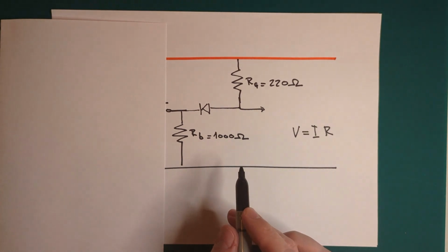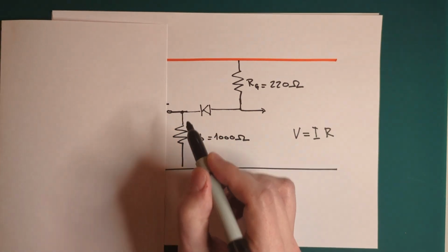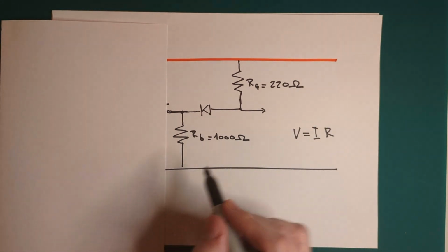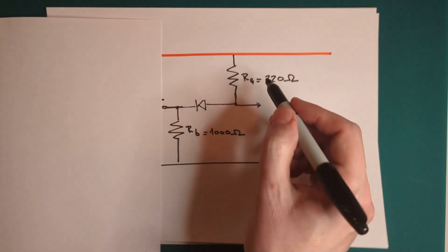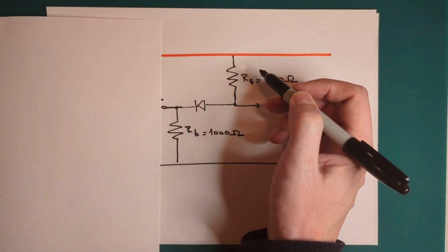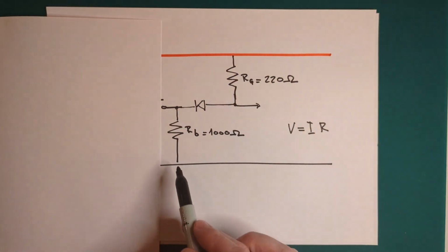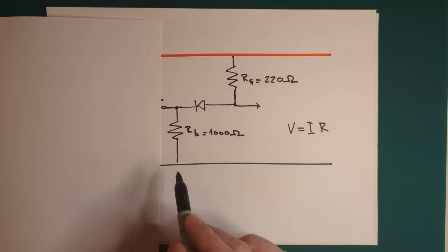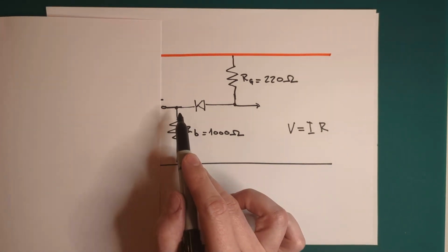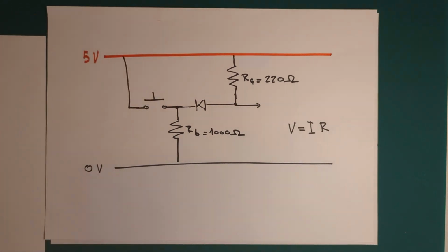Without doing the exact math, this is telling me that the distance between this voltage here and this point over here is going to be big, and the distance between this point and this point over here, 5 volts, is going to be small. Which means that this voltage will be closer to 5 volts than 0 volts, which is the problem I'm having. My low value here is pretty big, and this voltage is too high when the button is released, which is the situation we are considering.